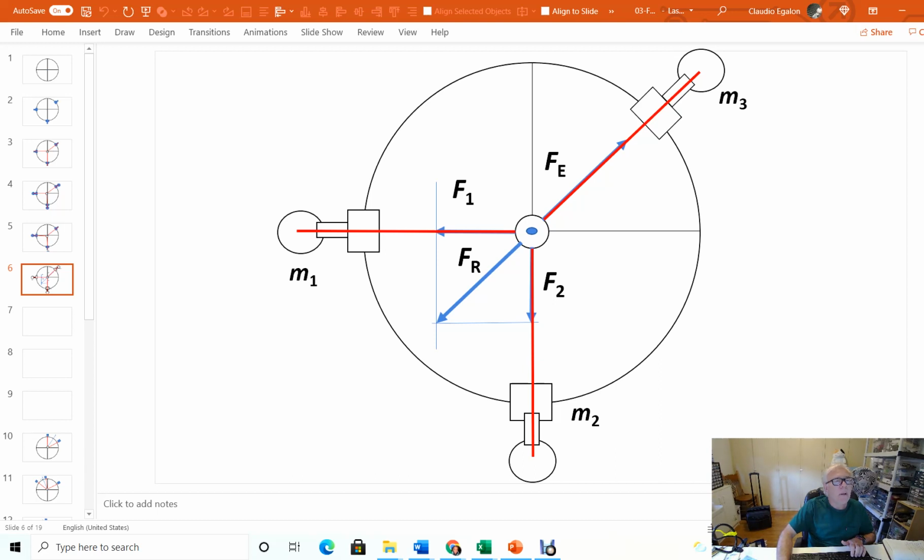And now you have to find an equilibrant force by finding the mass number 3 and its angle. That's basically how the experiment goes. And in the process, you have to weigh everything on the scale. Don't rely on the masses that are written on the slotted masses. You've got to use the scale to find out the value of the masses that you have there.